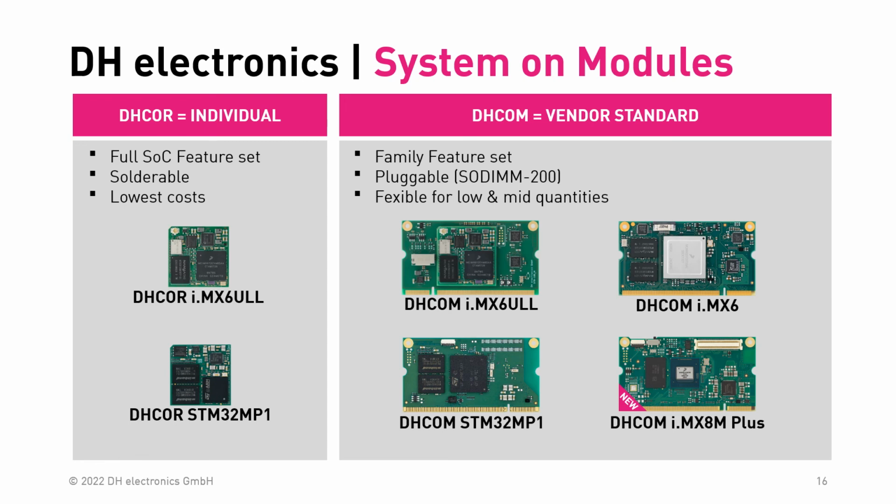We added an additional display bridge, which offers a standard RGB interface with the i.MX8M Plus and also optional DisplayPort connectivity. Overall, the SOM is very flexible and can be configured to your needs with our customer-specific variants. This configuration possibility applies to all our system on modules.